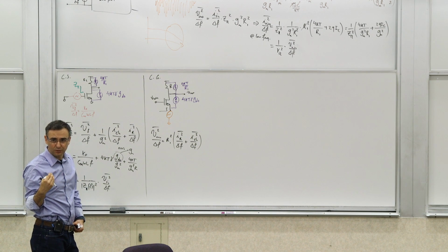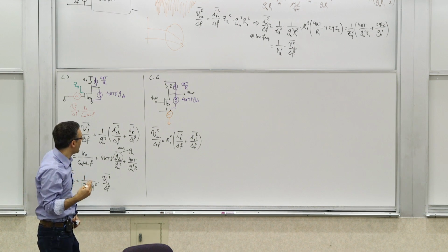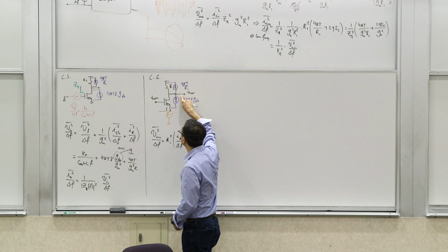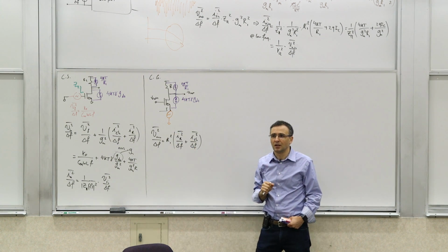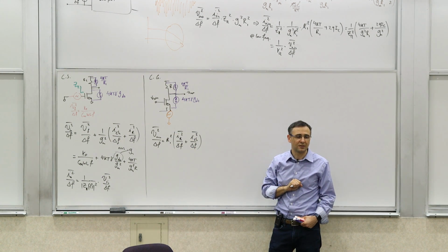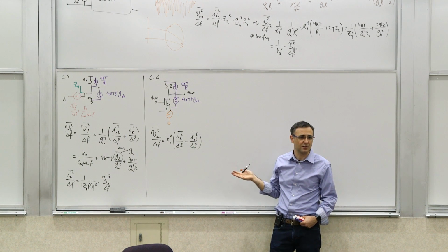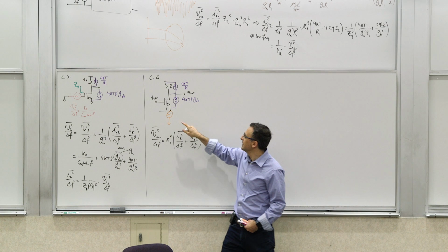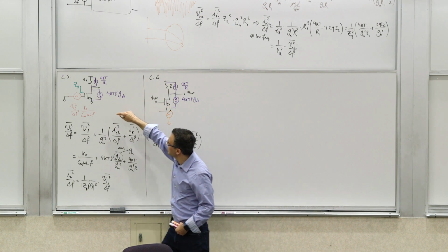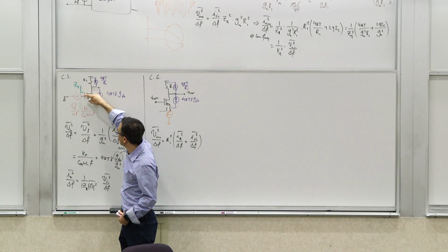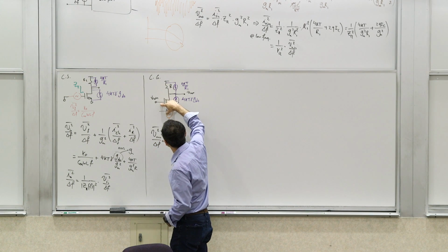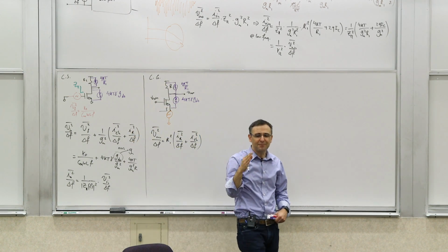I have a different input this time from the previous example, so I have to calculate the voltage gain from here to there. What is the voltage gain of the common gate? Remember, it's just gm R1. It's a non-inverting stage, because you're changing the VGS from a small signal perspective by moving this one up and down. It's a little bit different.